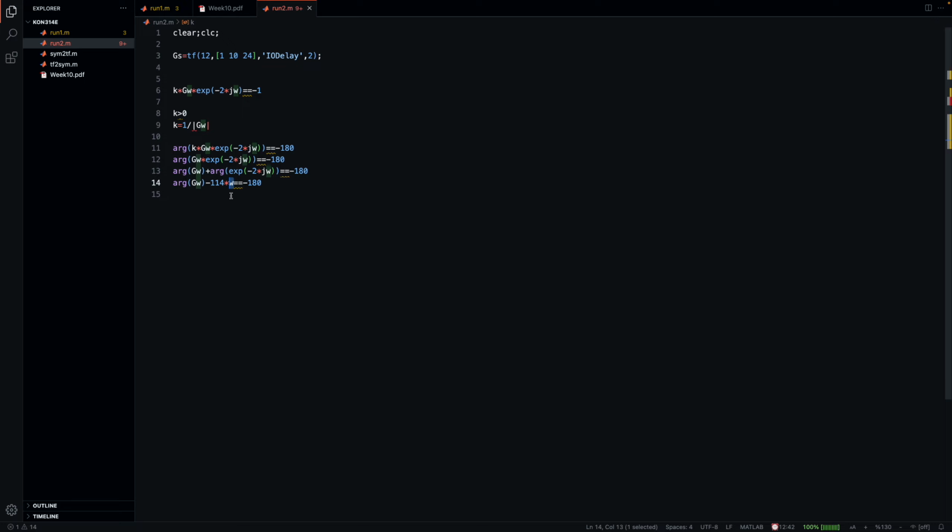And it can also be stated that if we, for example, add less delay to it, then, because this is directly 2 times omega, so tau omega, here we have tau. The less delay we add to the system, the less we restrict the system in terms of stability. So more delay means more destabilization of the system. So adding delay to a system is not a good thing. It will give up from its stability.